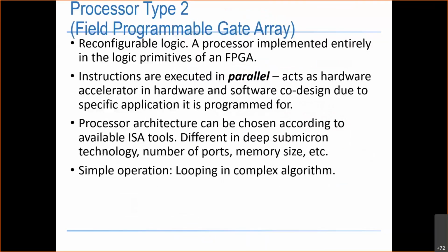All right. We also have FPGA. So I think maybe I've gone for some Verilog class or HDL class where you use FPGA. So FPGA is basically a circuit where you have unconnected gates inside. And you can actually download a circuit written in hardware description language such as Verilog or VHDL. And when you download this description of the circuit, for example, you describe an AND circuit, a decoder, a multiplexer, or something more complex like an adder and multiplier, or even more complex, a CPU. You describe it in a hardware description language of your choice.